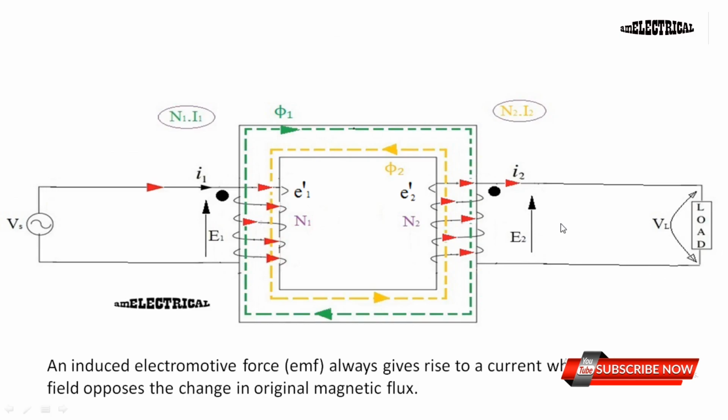As I2 current is flowing through the N2 number of turns, then according to the principle of Lenz, due to this ampere-turn N2 I2, a cancelling flux phi2 will be generated. Cancelling means phi2 is in the opposite direction of phi1. Now the question is, what does Lenz's law state? According to this law, an induced EMF always gives rise to a current whose magnetic field opposes the change in original magnetic flux.